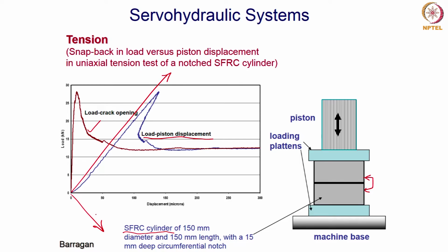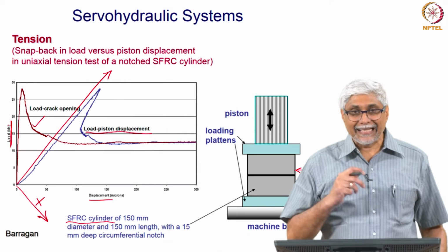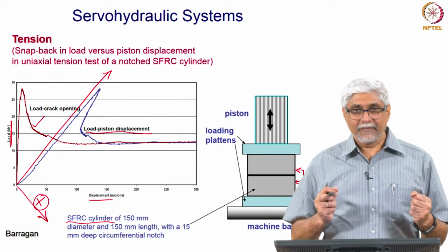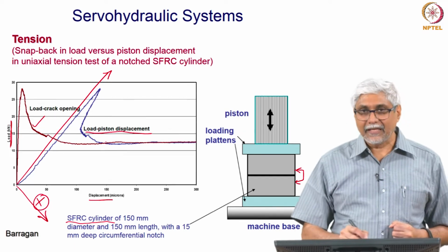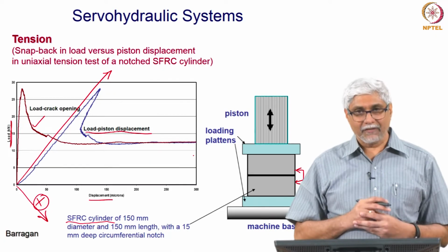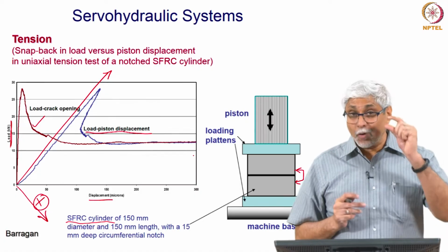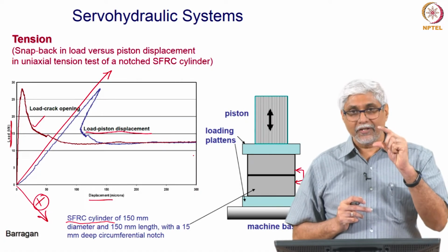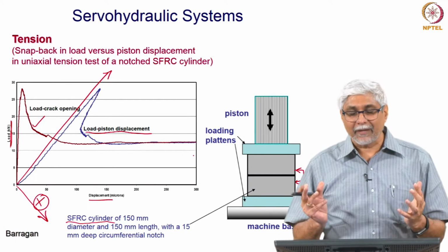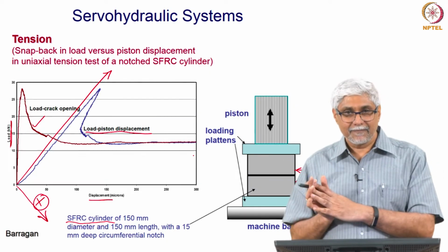Okay. So, I control this variable x, which has a component of displacement and a component of load, and I tell the machine to keep increasing this x in a certain way, and I will get a behavior that is now stable for the test to run, and then I can capture whatever response it is. Either I know exactly what is always going to increase and I measure that, or I look for a combination of parameters which is always going to increase, alright.